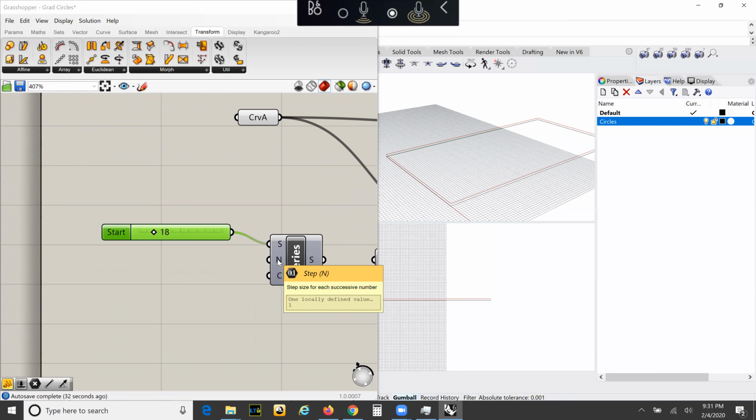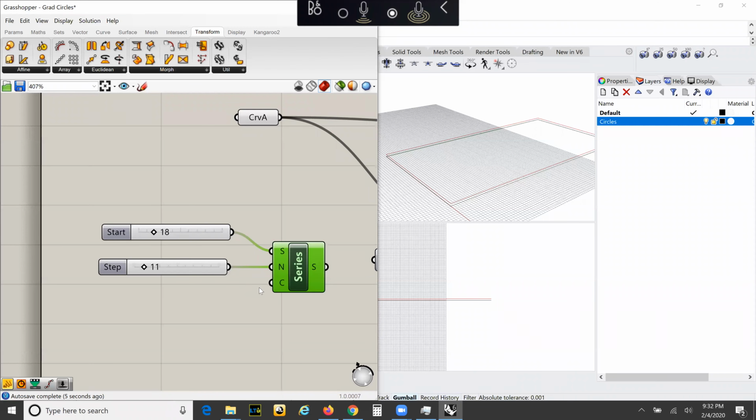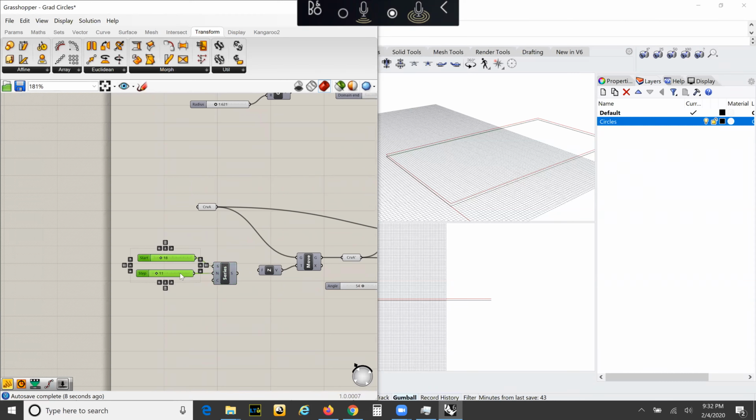And then we want the increments it goes at. For office, it's typically 14 feet floor to floor. For residential, it can range from 10 to 11, or sometimes as low as 9. But in this case, we'll go with 11. And so we'll crank that in. And how many floors do we want this tower? Well, the developer wants to make this a pretty big development, so we're going to make it 100 stories.